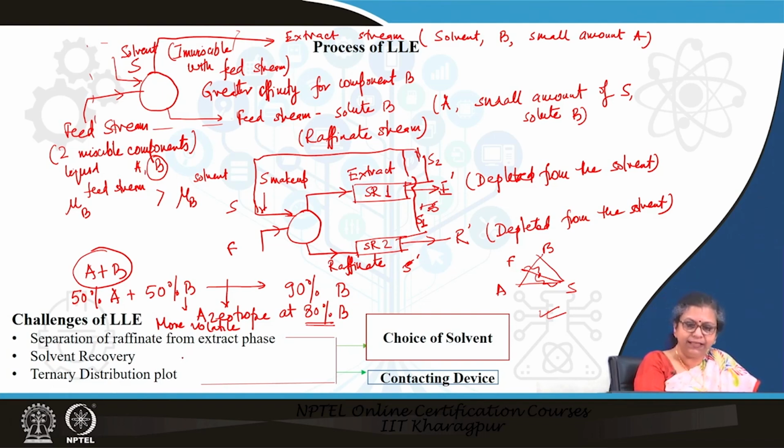So, therefore, due to these conditions, despite the limitations which liquid extraction has, which I have already told you, the primary challenges it has, liquid extraction is often opted for, and therefore, keeping the challenges in mind, we are going to address the design of different extractors. Challenges, I will repeat once more. First thing is separation of raffinate from the extract phase. This is a unique problem which you did not face for adsorption or distillation, and this is naturally due to the close density of the raffinate and the extract phase.